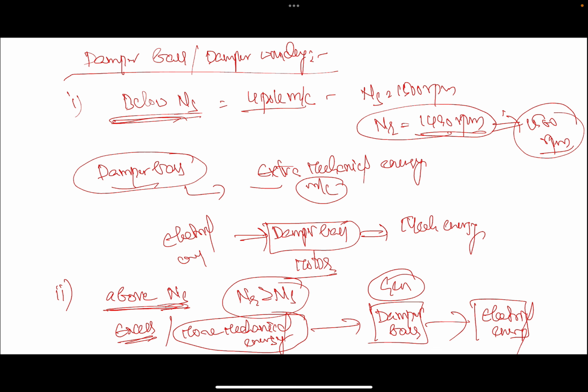When the rotor is rotating at synchronous speed, is there any work for the damper bars? I guess not. When everything is going on well, is there any need? So there is no need here. When the rotor is rotating at synchronous speed and it's magnetically locked with respect to the stator poles, there is no significance of damper bars.